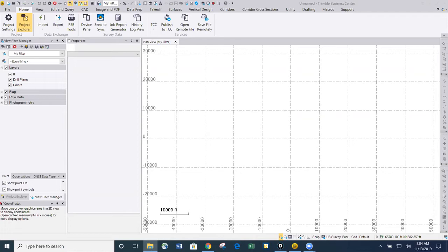In other words, one of the biggest challenges with data prep, in the way it's done today anyway, is that you add elevations to things, you put almost what we call static controls onto things to bring them up to the elevation or the location that the engineer specified. And the challenge with that is if something doesn't work quite right, in other words, you get drainage problems, or you've got something that needs to be redesigned, or you need to interpret a gap that was left in the design, then you need to start inputting extra information and manipulating the information you've already entered to make it work. And the problem with that is it's not parametric.